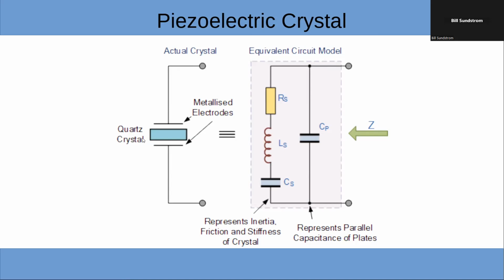It's essentially built as a slice of a quartz crystal that has metal plating on two sides of it in some kind of holder. And as you apply a voltage, it will cause that crystal to expand or contract depending on the polarity. And that will cause it to oscillate if you send it a signal in sync with the frequency it wants to oscillate at.